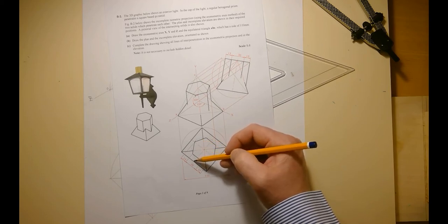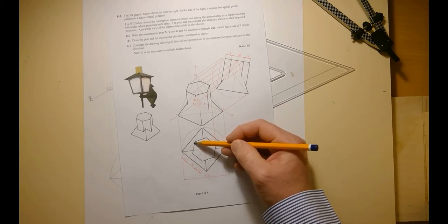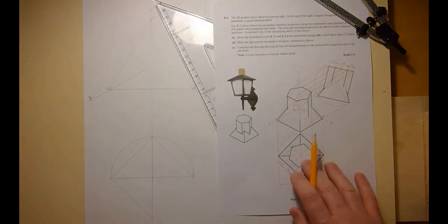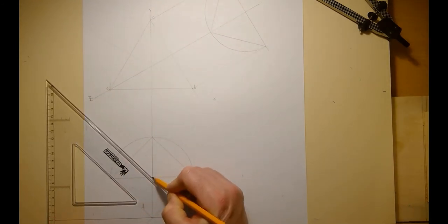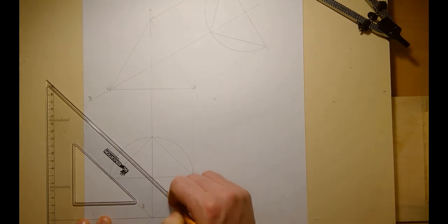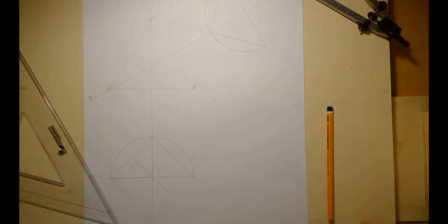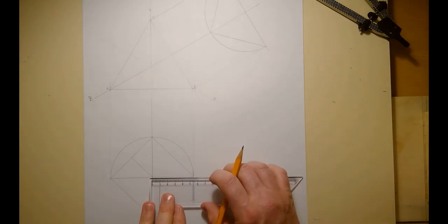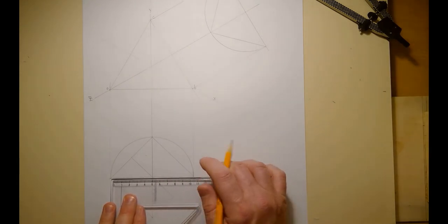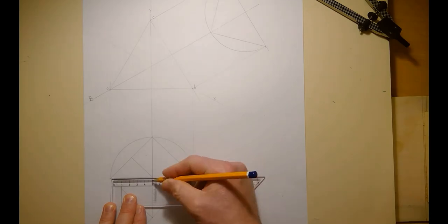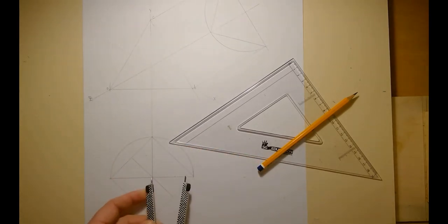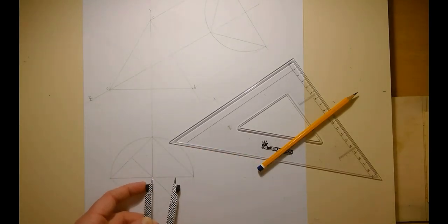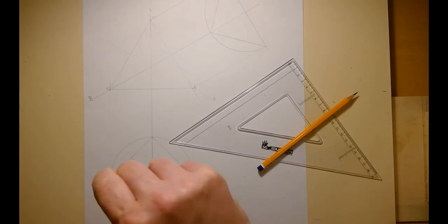Okay, if I wanted, I could step out my, say that's 30 there, then 15 and 15, and I could come up and mark it off. No real need to go into that trouble. So I'll just put in that line first. Okay, so that's that center line going across there. Okay, I'm going to set my compass now. Put a little mark on this first to show me, and I'll set my compass off that then. So a little mark 30 millimeters from the center out, and then I can use my compass, set it to that distance. Okay, set it to that 30, and I can draw my circle then.